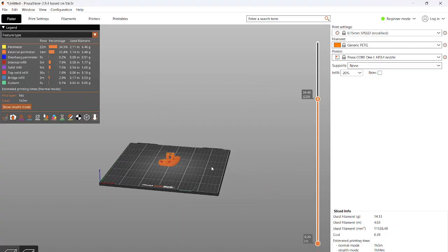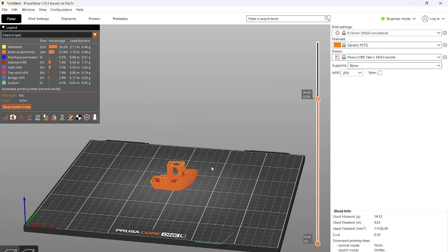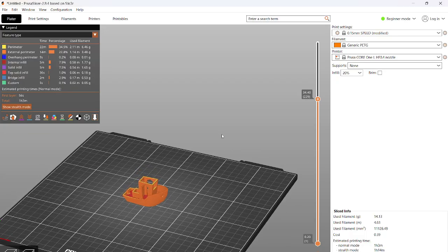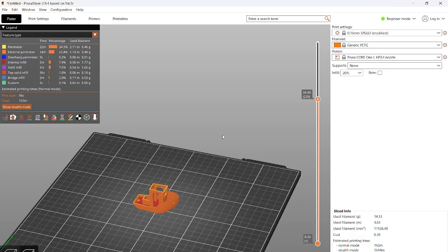I think it's becoming a little bit more common, but a lot of older files are STL only. But slicers can read both step and STL files. So if you want to give me a cleaner model, send me a step, because those will retain any curved geometry. All the faces are intact instead of being an approximation. I'm getting your exact model. So yeah, please use steps. But if you want to use an STL, you can.